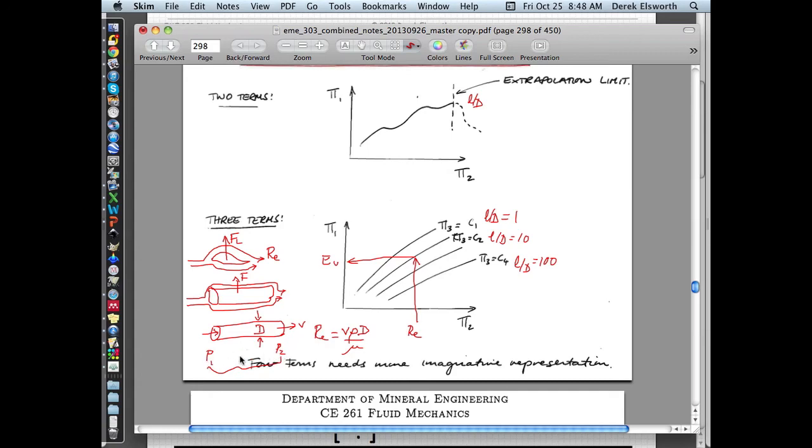If we measure the pressure drop between upstream and downstream, then we could also use an Euler number, which is equal to the difference between the upstream and downstream pressures, over the density of the fluid and the velocity of the fluid. It turns out that when we look at internal flows, it's exactly the same thing we're interested in. We're not so interested in the force put on the structure to lift this wing, but in the pressure difference between upstream and downstream, which, by the way, from conservation of momentum, gives you a net force you have to act against to hold that pipe static.